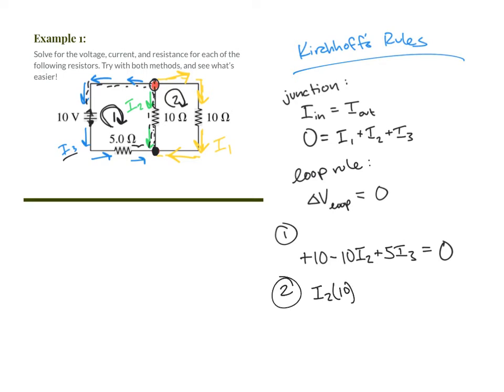And then we're at the other junction where nothing happens, moving around through the wire where nothing happens, down to this 10 ohm resistor. We are moving through this resistor the same way current is, so we are subtracting potential. The potential we're subtracting is I times R. Current is I1 in that section times R, a resistance of 10. And keep moving around the circuit, get back to the same point we started at, so the total must be